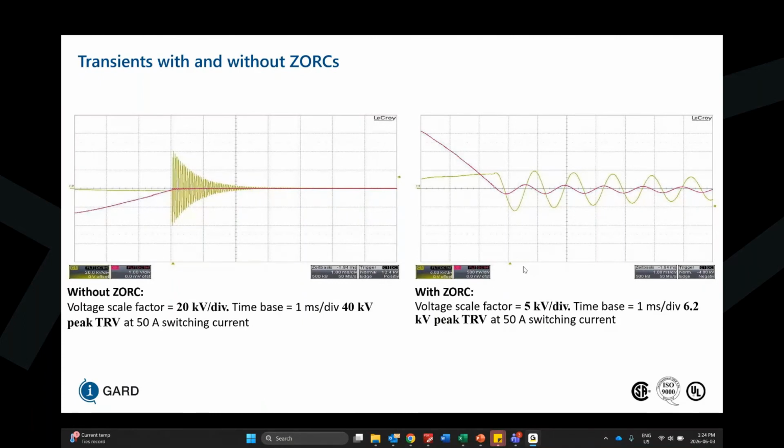But as I mentioned before, you have energization transients, which can be very high frequency for a very short duration. And then you also have de-energizing transients. That includes even if, let's say, you have a solidly grounded system and a ground fault occurs and the feeder breaker isolates itself.